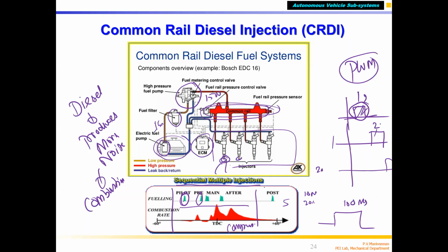Pilot injection is 10%, for example; I'm saying it can be different. Then the fuel is in very small droplets, and they start burning. So the combustion temperature already increases from 400 degrees. Since fuel is burning, it may go to around 800 degrees. After a few microseconds, you inject the pre-injection 20%. So this fuel will evaporate much more easily compared to the first. Because the droplets are small and there is already high temperature, around 800 degrees, combustion is happening, so this fuel will evaporate easily.